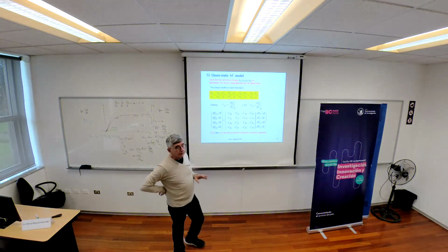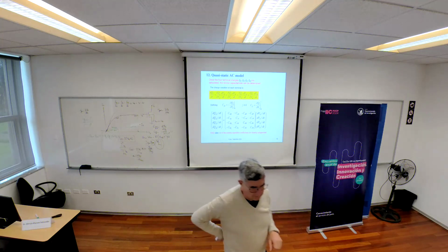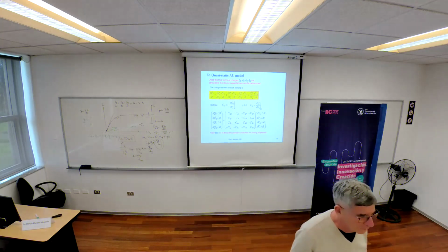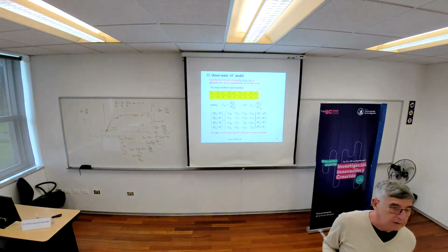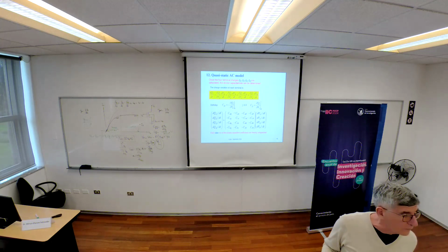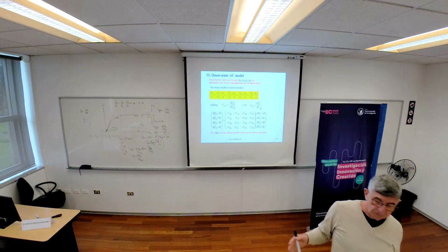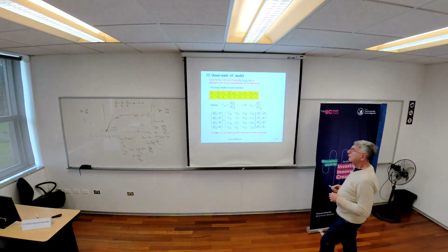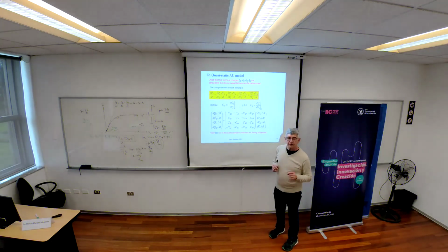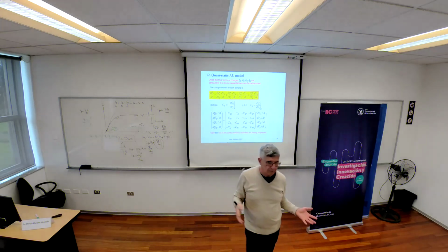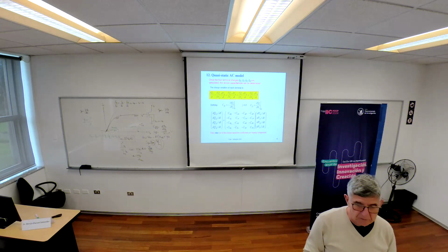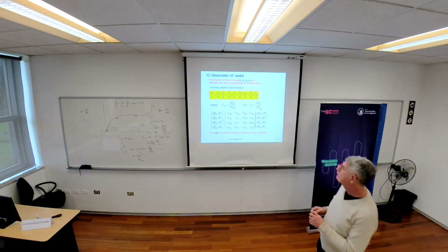So you have a total of 16 capacitors. Wow, this is a big problem. How to include all these capacitors to solve the frequency response of an amplifier or a current mirror or any device? Now, in fact, you have fewer independent capacitors. For example, in this line here, you have one capacitance which depends on the three others. It's exactly the same case as the transconductances.